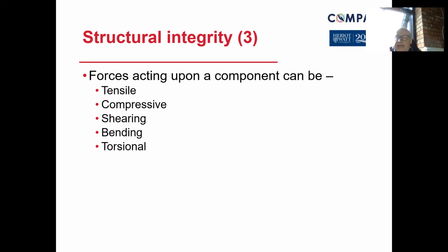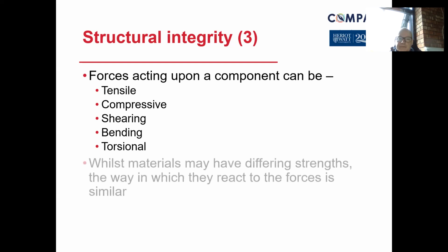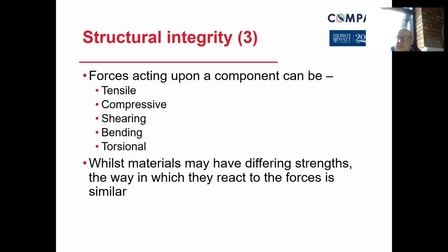And as a result of that, you need to make sure that people can then say the weakest link says the maximum we can lift with these component parts is 1/4 of a ton. Otherwise, when we do put it under these various strains and stresses, it's likely to stretch and break and fracture. So whilst materials may have differing strengths, the way in which they react to the forces is quite similar, and there's an expected interpretation of what that material will do.